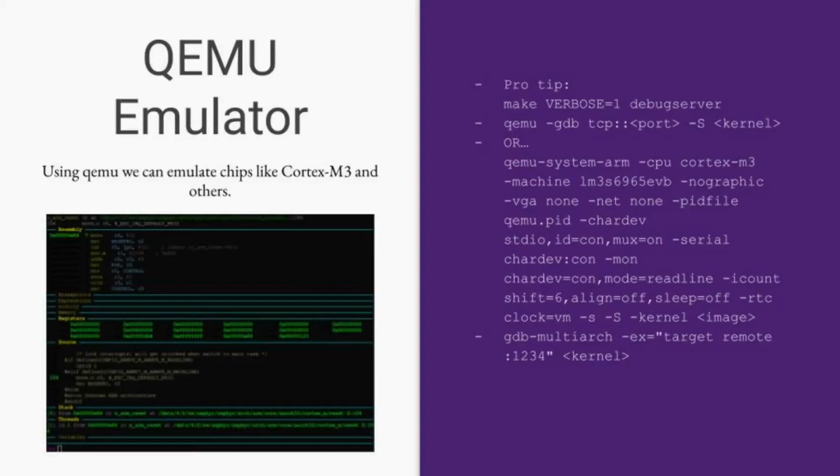In order for GDB to know which function you're in right now and show you the source code that is currently running, it needs to be able to read that from a program file. The file that you supply to GDB is not the program that's going to run, it's just the program that you're debugging, so that when GDB reads the current program counter from the hardware or from QEMU, it can then know where the program is right now in source code, and what function you're currently executing in.